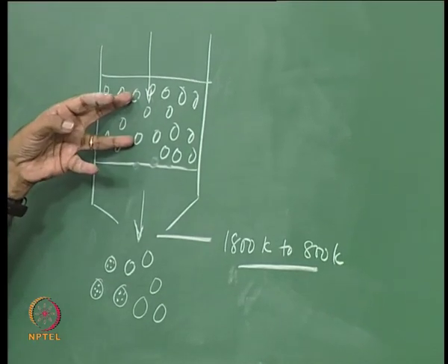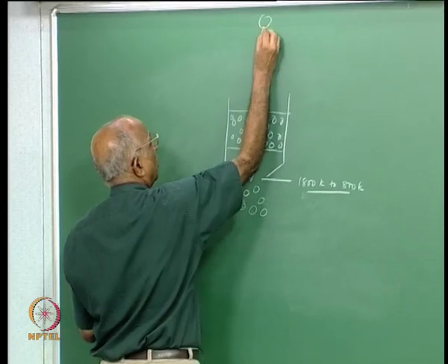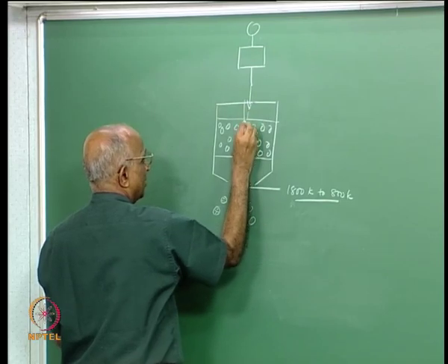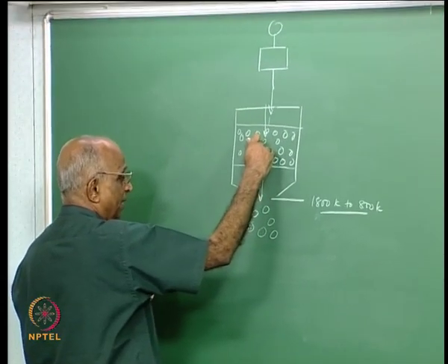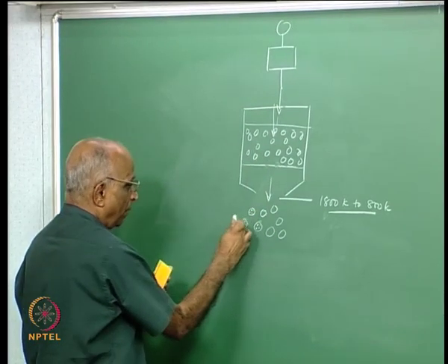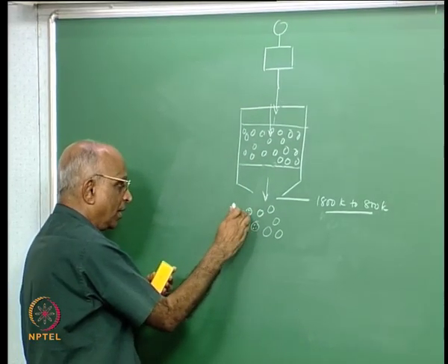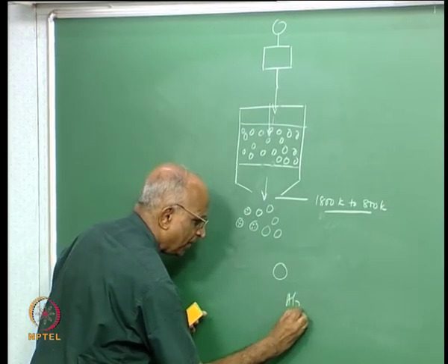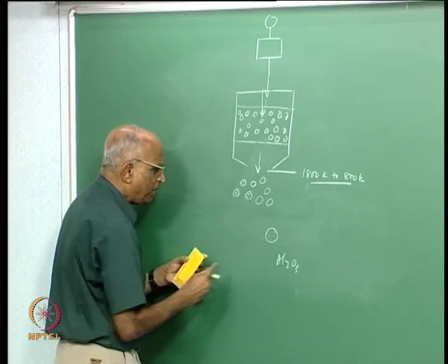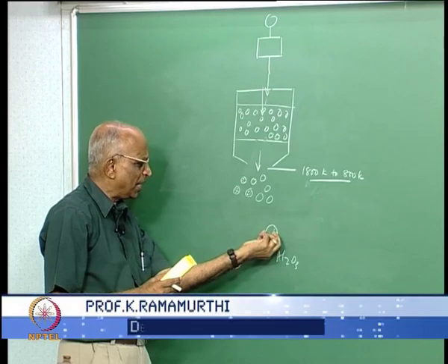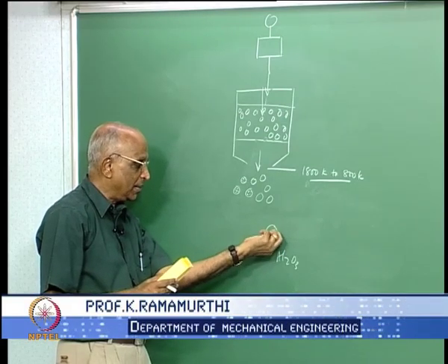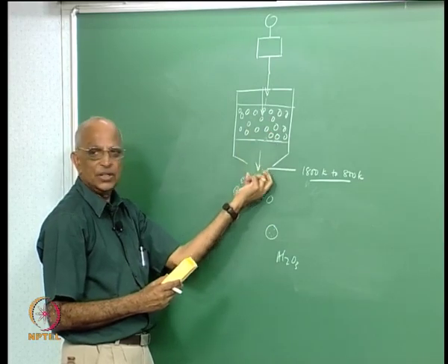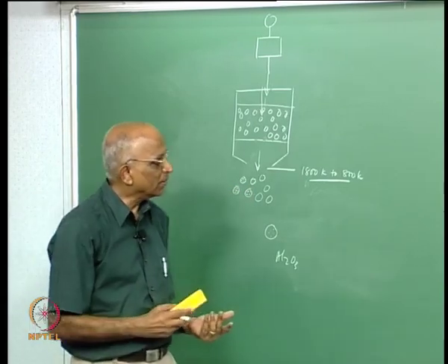Therefore this is the function. All that I now need is, I have a gas bottle, I have a hydrazine tank. From the hydrazine tank I inject the hydrazine into it, it gets into the catalyst bed, and reacts with the iridium in the particles of alumina which is impregnated into it. What we do is, we take this alumina, Al2O3, which is porous, I put something like hexachloroiridic acid and make sure that when I treat it I get iridium which is available on these crystals and inside the pores, and when hydrazine flows it decomposes.